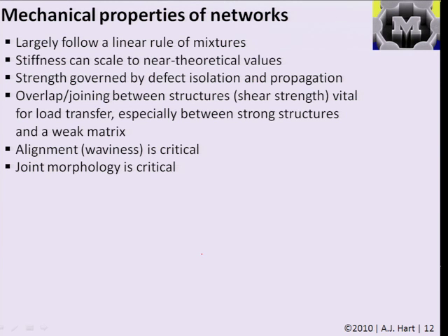So we can think of this property, for example, the stiffness or the strength at low concentrations scaling by a rule of mixtures, where you would have a linear relationship, for example, between the modulus or the strength and the percent you would have in the material. There are limitations and extensions to this in a lot of specific cases. But in general, if you took this to a limit of highly aligned structures and highly organized continuous structures, we would find that the stiffness of the material can scale to near theoretical values, just as we saw for mechanical properties of individual structures.